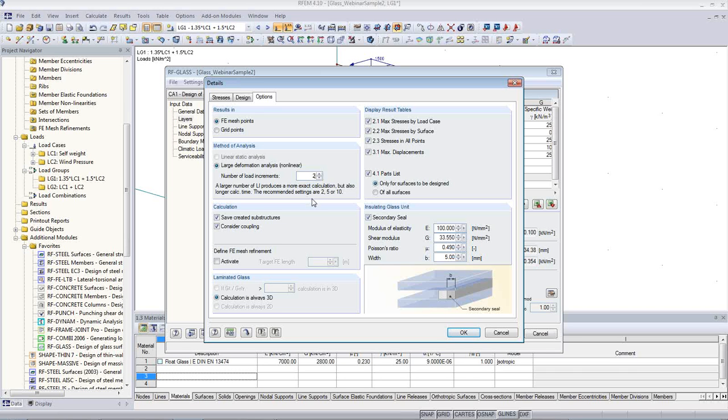This may have an effect on the results, so as well as the mesh density and the number of load increments, it is an important little control that you can switch on and off or influence. You may try out yourself whether it has an influence on the results or not. Typically, we recommend to have a reasonable mesh density, which is dense enough for the structure. You can find that out by gradually increasing the density, and if the results significantly change, then obviously this has an effect.